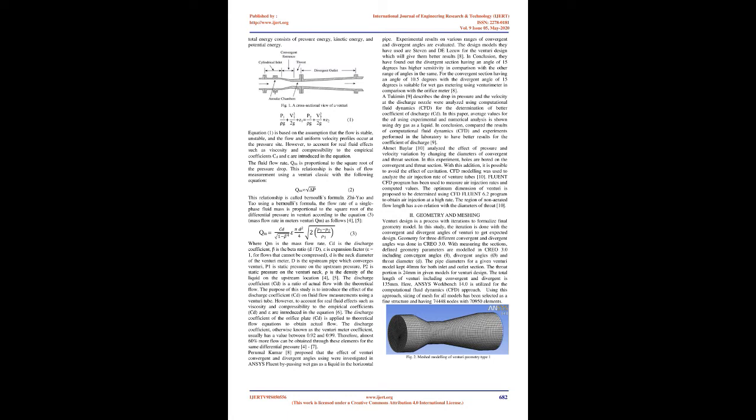The conditions encountered in thick liquid metering can be beyond the scope of application for industry standards, ISO 5167-1 [2]. Venturi meters have convergent cone inlets, cylindrical necks, and divergent recovery cones. It has no projection to the liquid, there is no sharp angle and no sudden changes in the contour. The following Fig 1 shows Venturi meters with uniform cylindrical parts before converging, neck canal, and divergent [3].